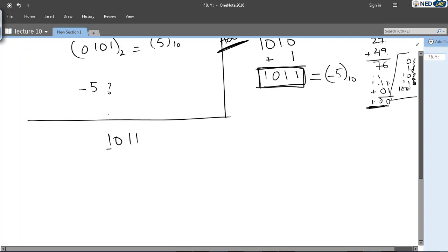Actually it's also a sign magnitude format, but this bit, the most significant bit, has a sign and magnitude associated with it. Since it is representing a negative number, we have 4 places, 1 2 3 4. This bit will represent 1, this bit will represent 2, this bit will represent 4, and normally this bit would represent 8, but since it now has a sign associated with it, it represents minus 8.